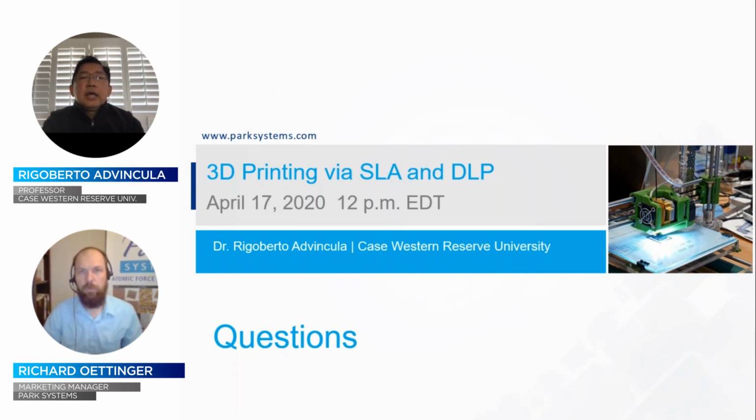Good question. The surface tension of the polymer is very important during mixing. So when you have mixing of this resin and filler materials, you want them to be as homogeneous as possible, because any phase separation during printing will be a failure in terms of either side reactions or incomplete or inhomogeneous distribution of your filler material.